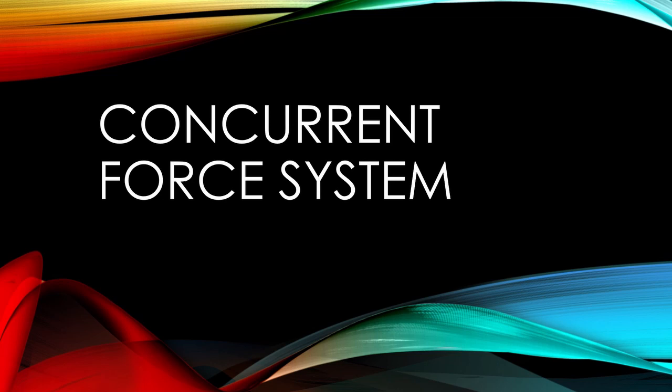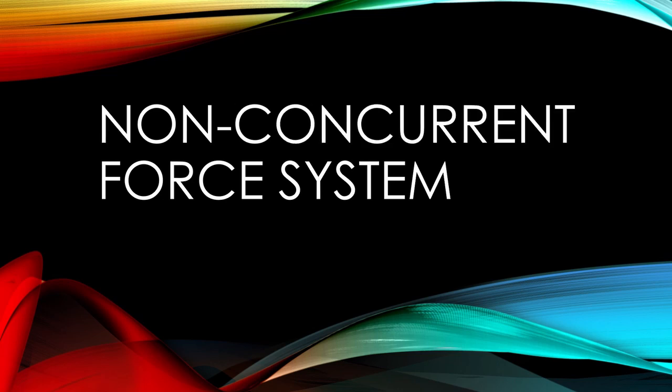We have two types of force systems: concurrent force system and non-concurrent force system. Concurrent force system: a system in which the lines of action of all forces intersect at one point. In a concurrent force system, the force vectors can be added together as a single resultant force. Non-concurrent force system: a system in which the lines of action of all forces do not intersect at one point. In a non-concurrent force system, the force vectors cannot be added together as a single resultant force.